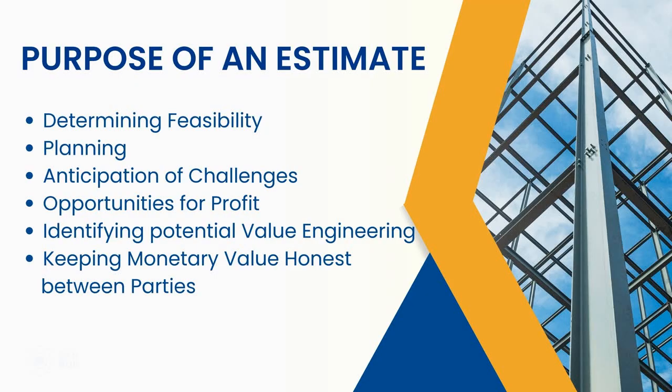Value engineering is not taking money or items out of the contract. We want to be very careful about removing scope of work because we often don't see the full value of that scope of work reimbursed as we remove it out of the project. When we're value engineering, we want the same level of integrity and quality but possibly by using different materials or methods that's going to reduce the cost in the way that we're doing business. And then keeping monetary value honest between parties.